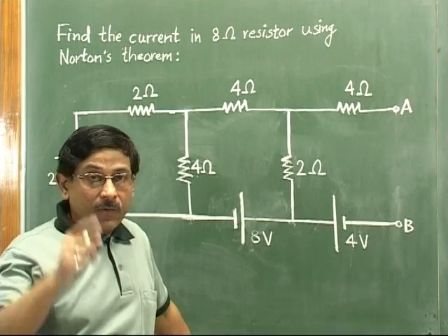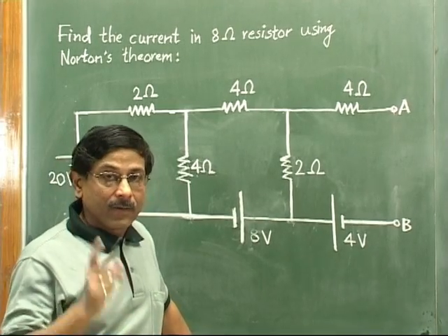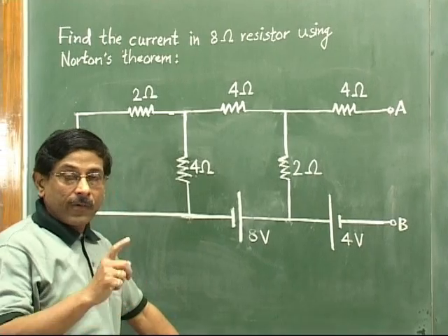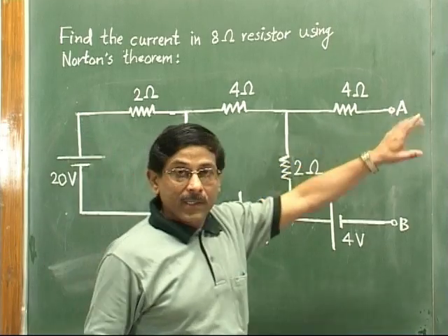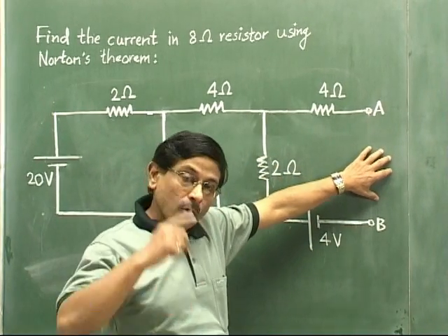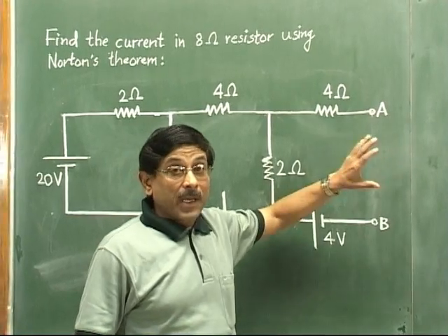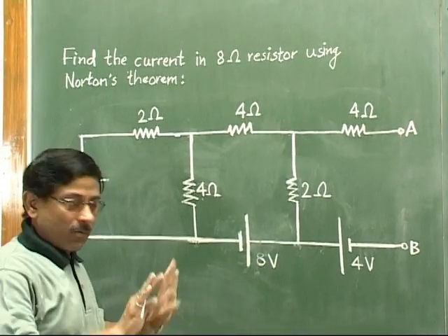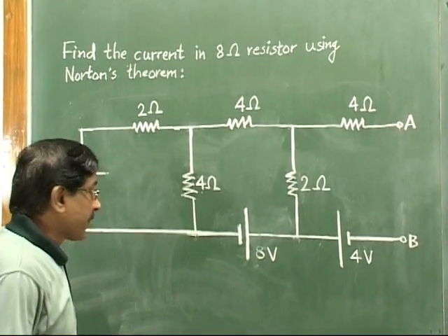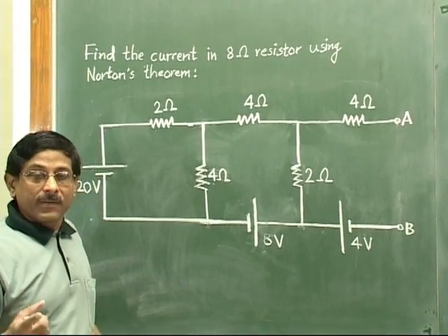Okay, so for finding the value of RN, Norton's equivalent resistance, we have taken the initial circuit. Which circuit? After removing the load resistor. One more thing is remaining. We want just a passive circuit. That means we don't want the voltage or current sources, or the power sources in general. What is the basic rule that I have told?